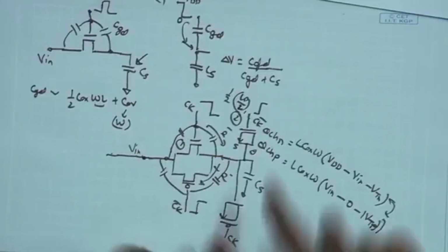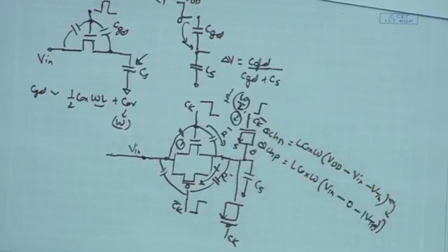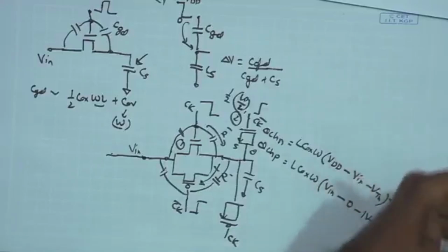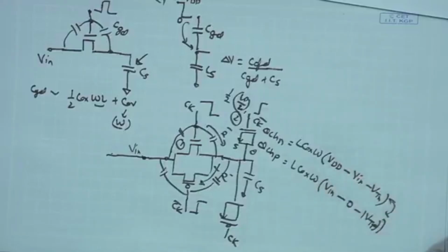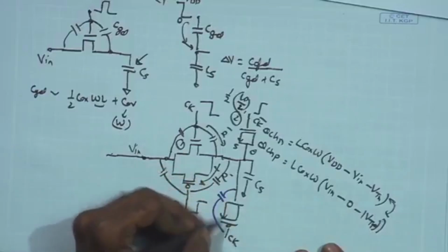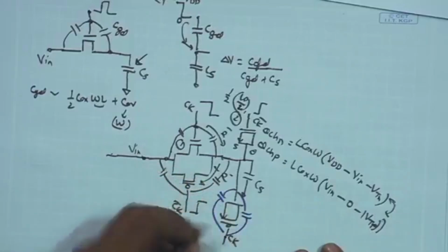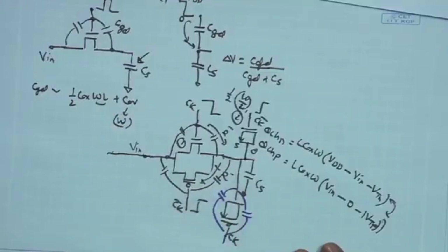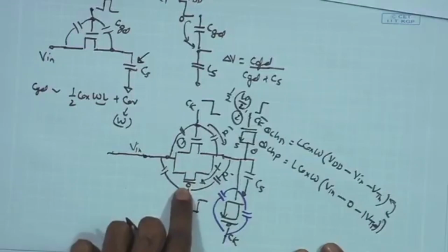Also, we can see if this configuration can also help us in mitigating clock feed through, because if I look at the capacitance for one of these devices, the CGD of these devices will be the combination of CGS and CGD, the total capacitance, and the W of this one is half the W of the PMOS over here.